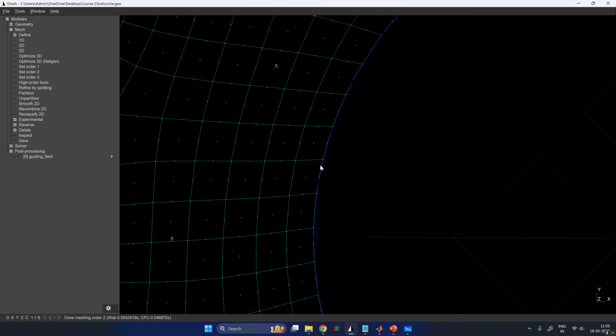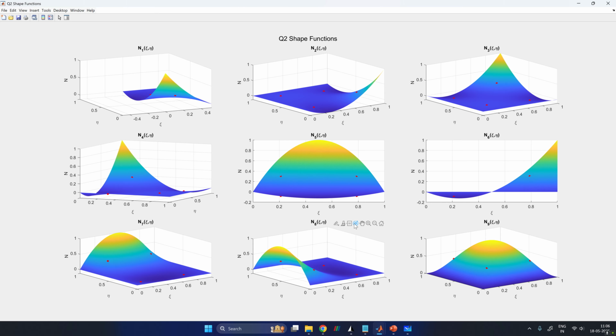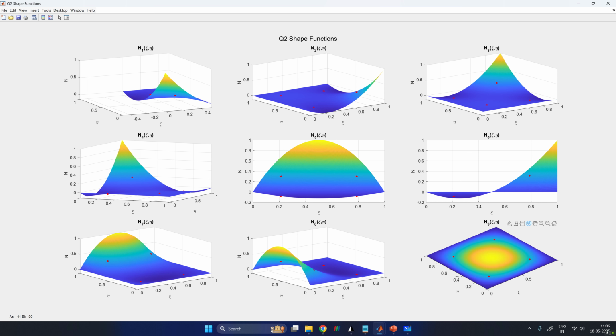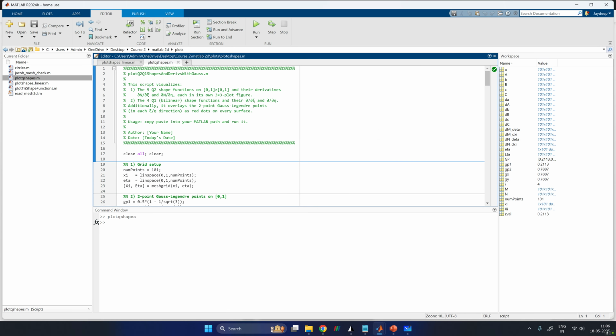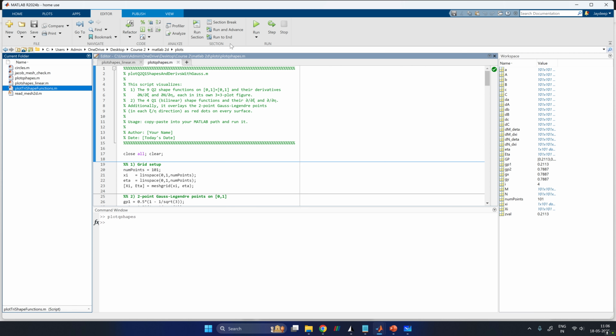In the 2D case, we'll have a boundary integral, and we'll have to integrate this line, a 1D integral, and then add it to the element. In case of 3D, it will be an integral over a 2D face, which will be added to the 3D element, which we'll see. We'll use tetrahedrons in that case. So these were your quad shape functions up to second order. I have not shown the third order here, but the idea is the same. Let's look at triangles.